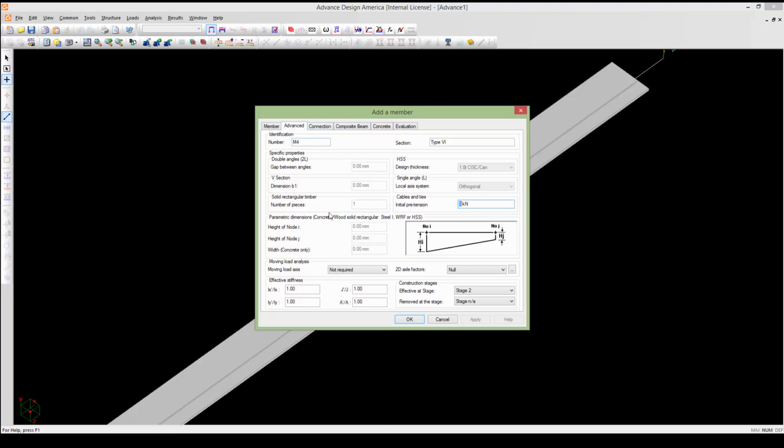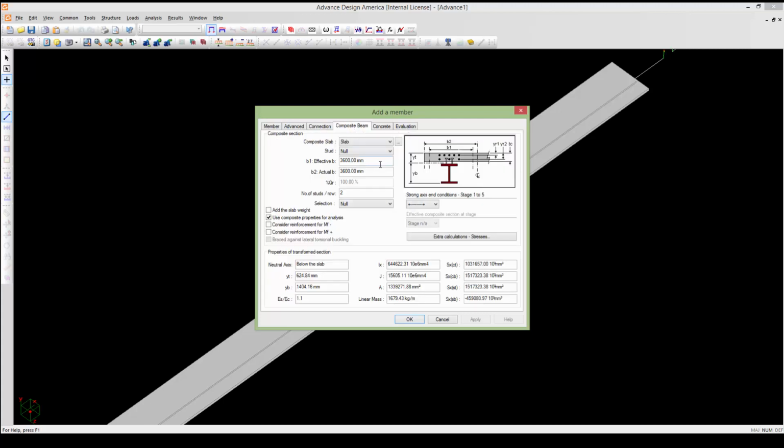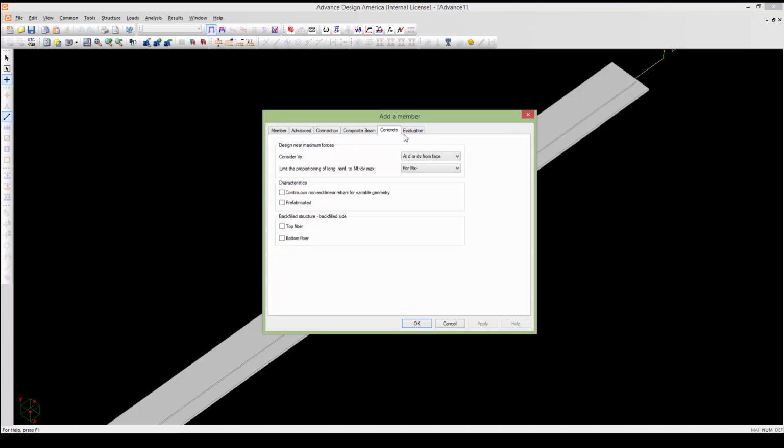So these small beams will be activated from stage 5. And also these are okay. For this member, I will change this to hinge because before stage 1 to 5 they are not there, so I don't want to have some restraints on my moment. Others are okay.